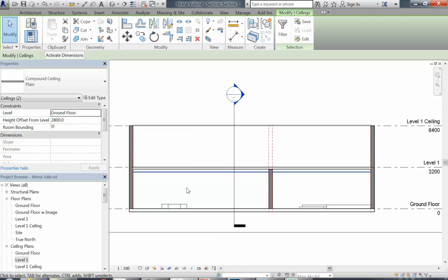So probably your levels. You need to probably go back to the way you've done your levels. But like I said, you can go over the recordings I've done and that'll maybe clear up those things. So the recording I did last week. Yeah, your levels, this is what I did at the beginning. So your level is too low there. Level 1's too low. That's why you're getting the warnings.